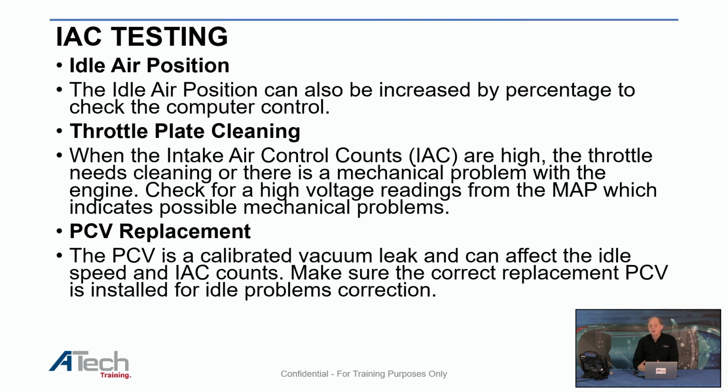The thing about right now is PCV valves are not easily removed, so they're not being addressed as much as they were before. So my suggestion for you is if you have a drivability problem, it's idle air control. Before you go any farther, check the PCV valve system, and on some of the European cars, you're going to replace the whole valve cover or the cam cover on the particular system. It's kind of neat to look at it.